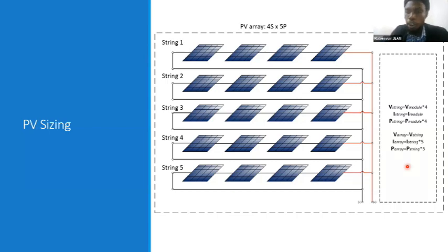But first of all, we have to determine, according to the historical consumption of the client, the amount of energy required by the client during a day. So we can know the available energy during a day according to the irradiance information. Once we have the range of time where sunlight will be available, we can approximate the power of the system.